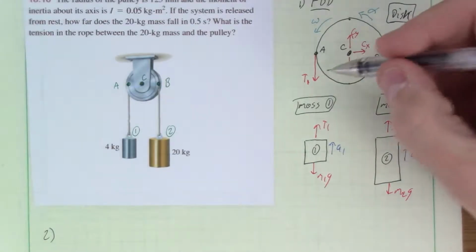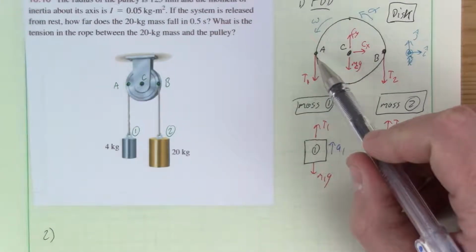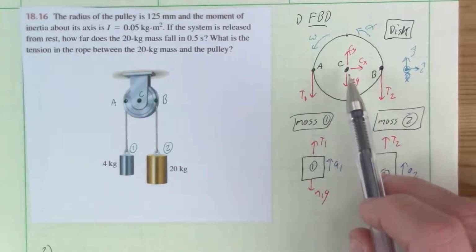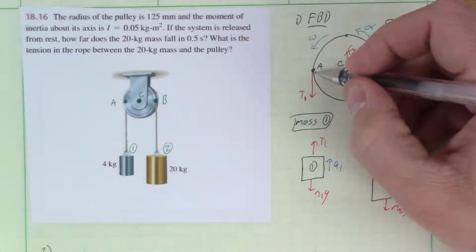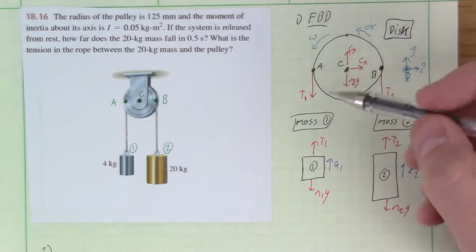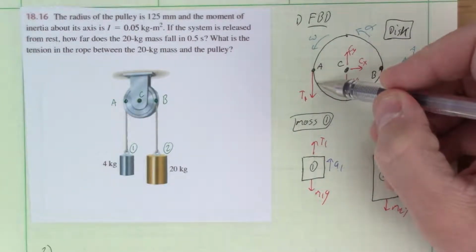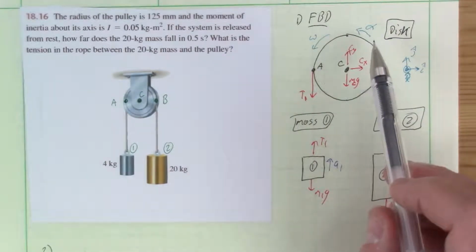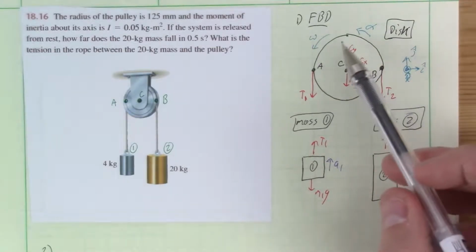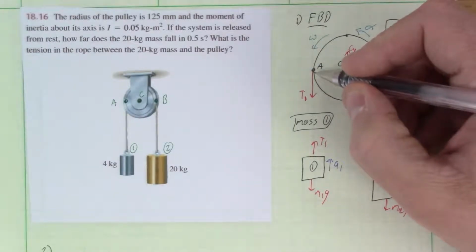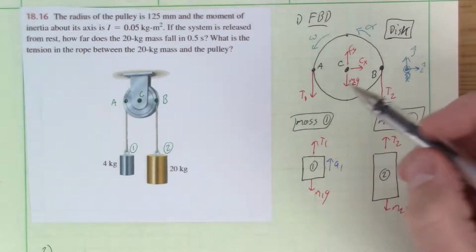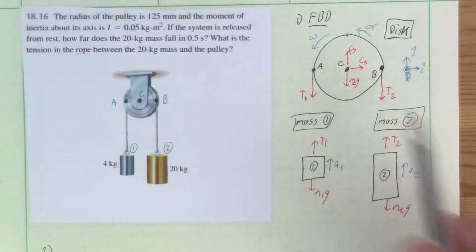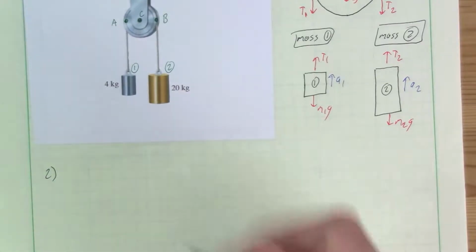Now, let's get some intuition here first. Like, what do we expect the acceleration of A to be? Well, C is not accelerating at all because that's a pinned point, right? So that one's a static, it's a fixed point essentially, right? A is probably going to be, well, like the next instant of A is going to be moving down to here, right? As the pulley rotates along the direction we're assuming omega and alpha to be, right? So if omega is positive, A would then be moving down to here. So just the acceleration at this point is probably going to be pointing inward a little bit while also heading downward here. Well, let's see. Let's work through this. What do we actually get?